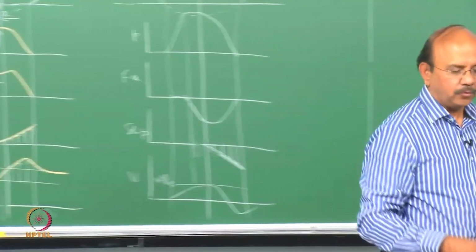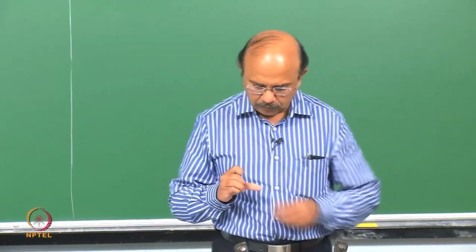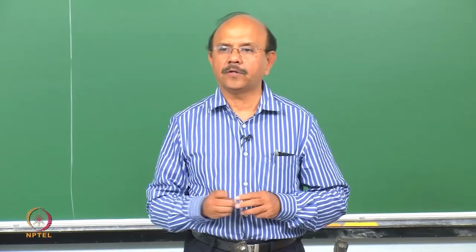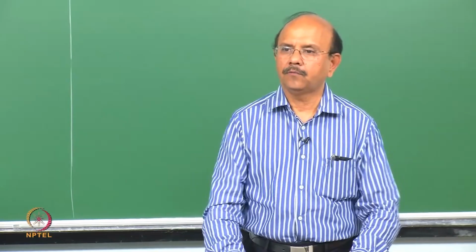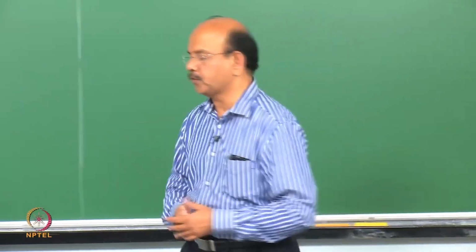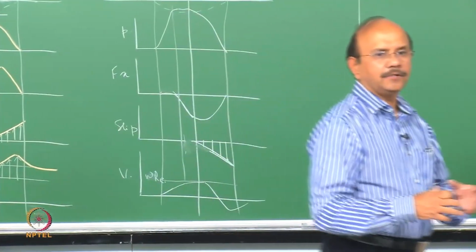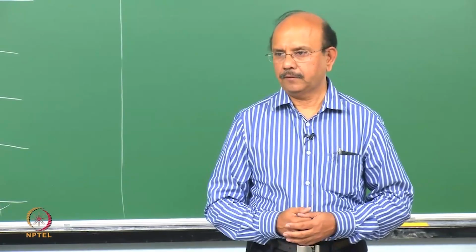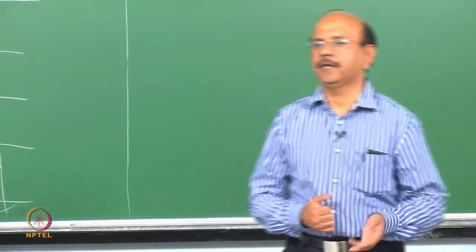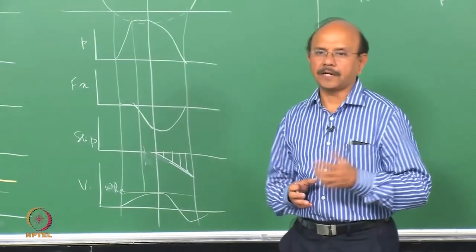One of the key things that you would have noticed is what is called the aspect ratio, and we will look at the aspect ratio effect on rolling resistance shortly. By aspect ratio, we mean the ratio of height to width. This is typically of the order of 50% in passenger car tires.